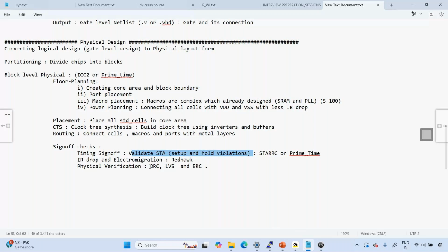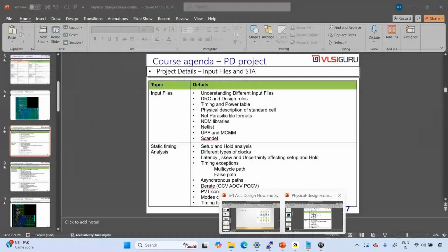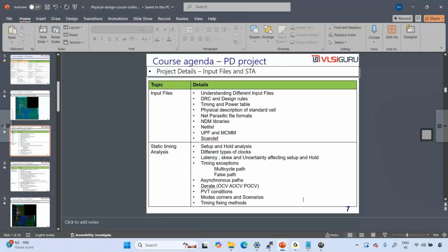So according to me, 7 nm and 14 nm don't have any drastic changes. They have almost same issues, but from 14 to 5 or 3 you have more changes. You have drastic changes from 5 nm to 14 nm. So double patterning will come into picture with 3 nm, 5 nm.